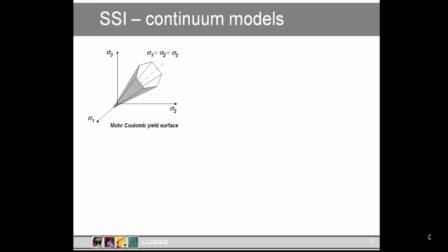And this illustration shows the yield surface, and it's about now that many people start to tune out and think that this is probably quite academic, and we're going to start talking about yield, which is based on a critical shear stress and pressure dependency and all those things. But thinking practically, what this illustration is telling us is that the strength of the material increases with balanced confining stresses. So the strength of the soil is greater as we go deeper into the ground, which of course we know.